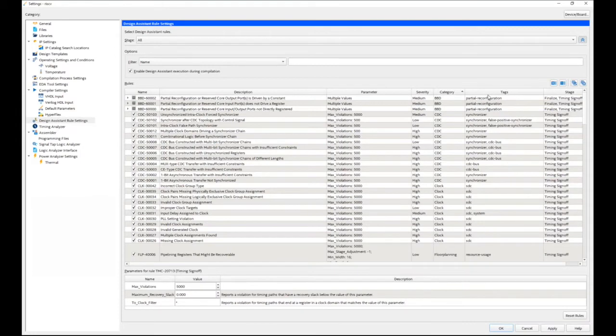In particular for Quartus Standard, this person is asking. That would be in the timing analyzer, but it looks like you're asking about different parts in particular. I see -C7G, -C8G, -I6G, so we are talking about commercial and industrial grade parts.